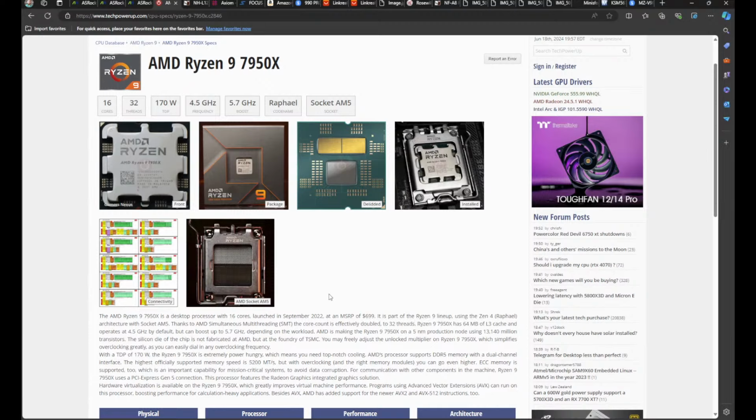definitely great for gaming. In fact, you don't even want to get the 7950 because it has two CCDs. AMD uses a chiplet design on their processors. So 8 of the cores are on one chiplet, 8 of the cores are on the other chiplet for this 16-core CPU. But on this CPU, if you buy the X3D variant that has the 3D V-cache, they only put the V-cache on top of one of those CCDs. So only 8 of your cores can take advantage of that. And there's all this logic and special driver that's required for Windows 11 for it to be able to figure out when it should use the cores with the 3D V-cache.